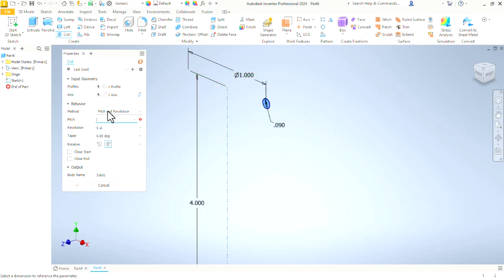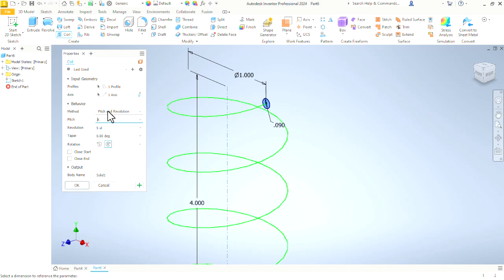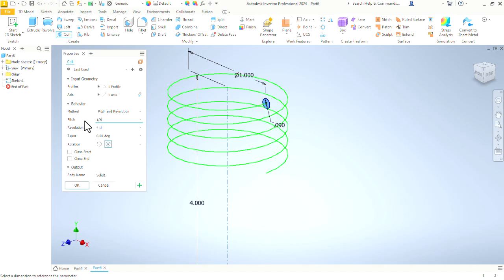While we're looking at fractions here, let me show you one thing real quick that Inventor can do. I know that 0.5 is 1/2 inch. I can also work in fractions, enter 1 divided by 2, 1 over 2, and there is my 1/2 inch, and it shows me in that little pop-up there that that pitch is 1/2 inch. I can make it 1/8 inch, and it shows me that it is 0.125. Inventor will help you out by doing the math for you.